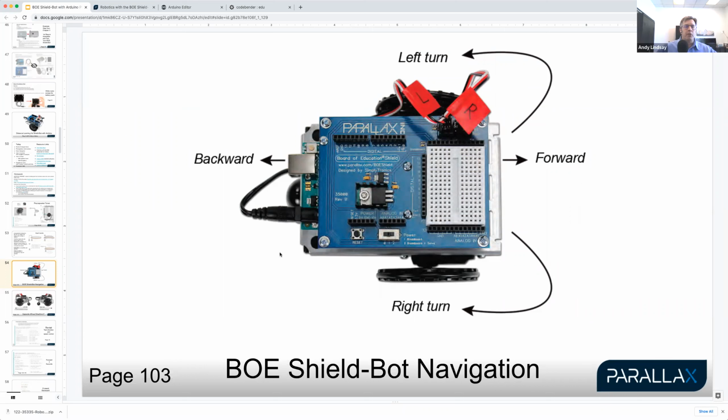No combination of plugging and unplugging those cables can hurt the robot or your computer. However, actually, all right, I'll give you one rule, and that is if you're like this with the battery power disconnected and the USB power connected, try to keep the 3-position switch right here in either position 0 or 1. We don't want to have it in position 2 if you have a sketch that's running the servos, because we don't want to try to ask your computer's USB port for enough power to run these servo motors. So I'd say that's probably the most important thing to keep in mind.